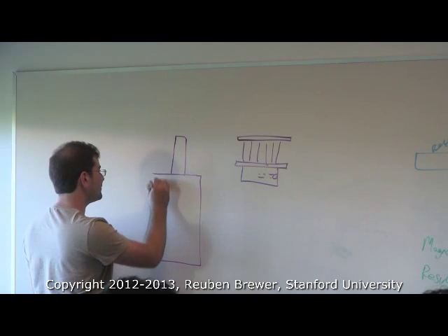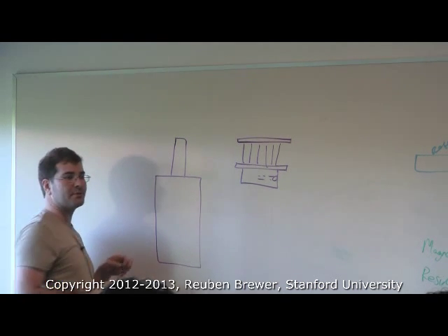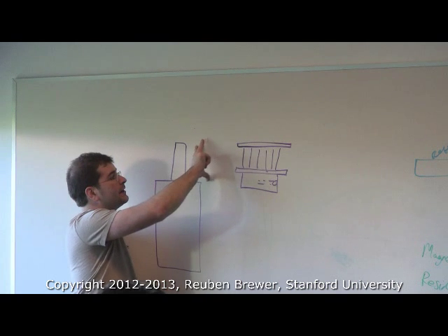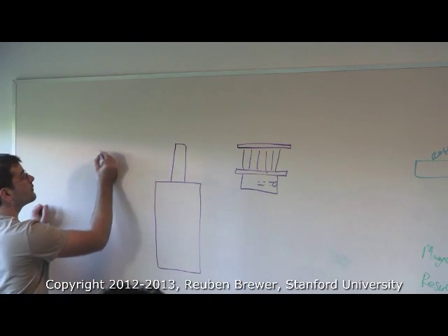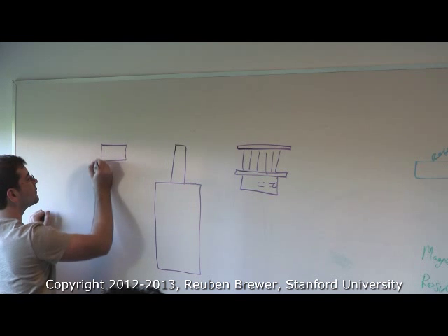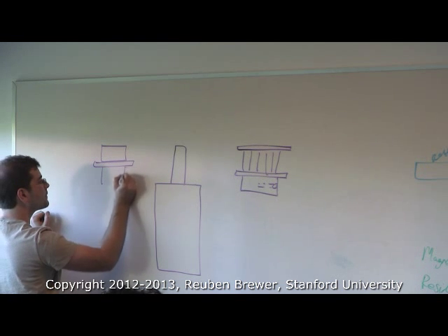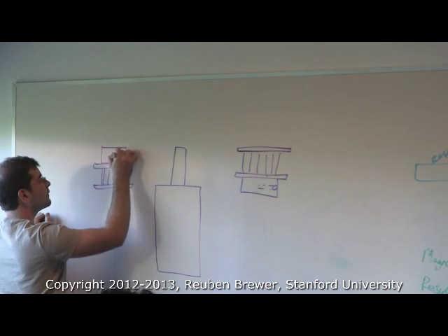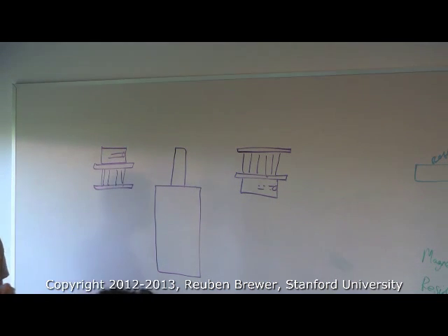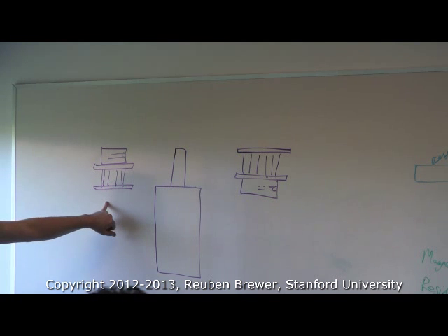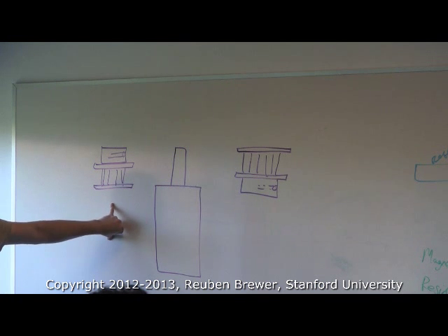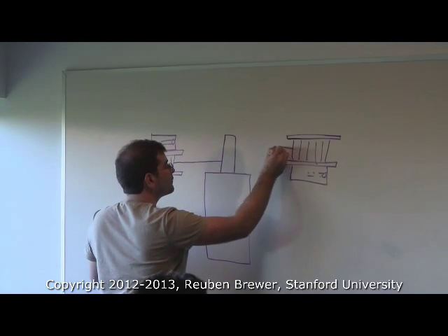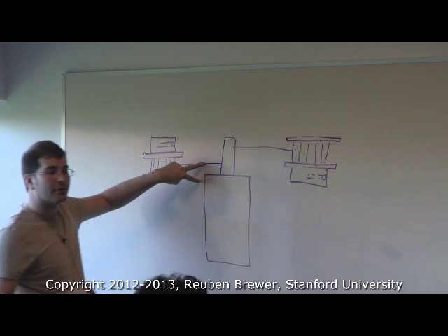Now we're not going to change anything about the motor. This is a thought experiment. I'm free to put this on this way or to flip it upside down and put it on this way. Which is better and why? The left. Why? Because if this is the center line of my force, this is a lower lever arm.